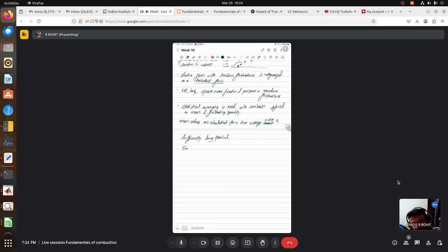Then the time average for pressure, in a sufficiently long time period, say a long time interval, say you have T2 minus T1, that is nothing but delta T. For a given delta T, the mean value or the time average value can be written as 1 by T2 minus T1, integral T1 to T2, the pressure value at each instant.